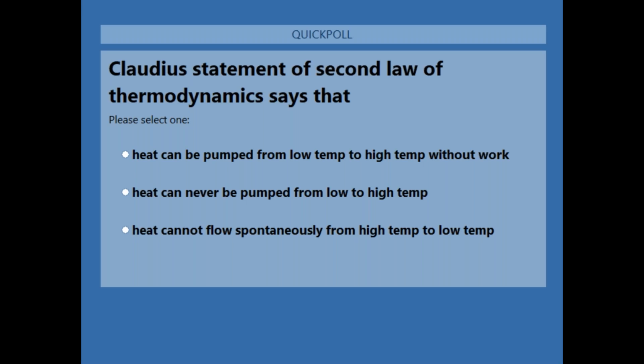So what does the refrigerator do? It takes the heat from the freezer section, which is at -5 degrees centigrade, and it throws that heat to the surrounding outside, which is at a higher temperature of 25 degrees centigrade. Now, how does this happen? This happens because you are supplying electricity to the compressor. If your compressor is shut down, or if you are switching off the switch which supplies electricity to the compressor, this phenomenon would not happen. Okay, so the fridge would operate and it would cool the freezer only if your compressor is on.